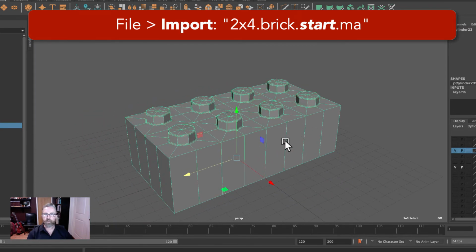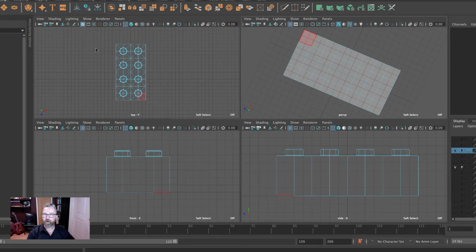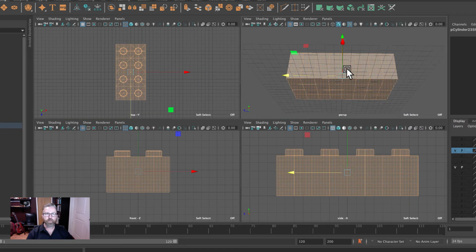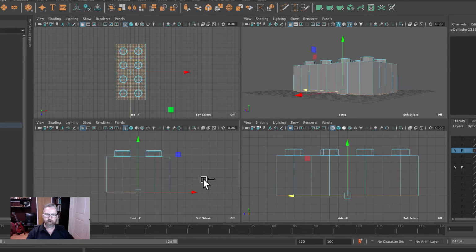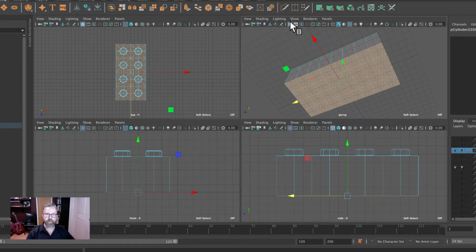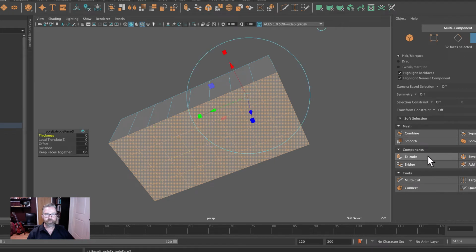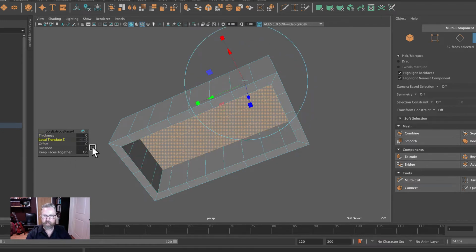and we'll create the recessed version. Now we can select all of the faces, right? We'll draw a big bounding box around all of the faces. We only want the bottom, so we'll now use the control key to deselect all the top faces. That leaves us with the bottom set of faces. And we can come to the modeling toolkit and we'll hit extrude twice. The first time we'll create the offset of 0.8, right? Offset of 0.8, and then we'll extrude the second time, and our local Z translate is -4.